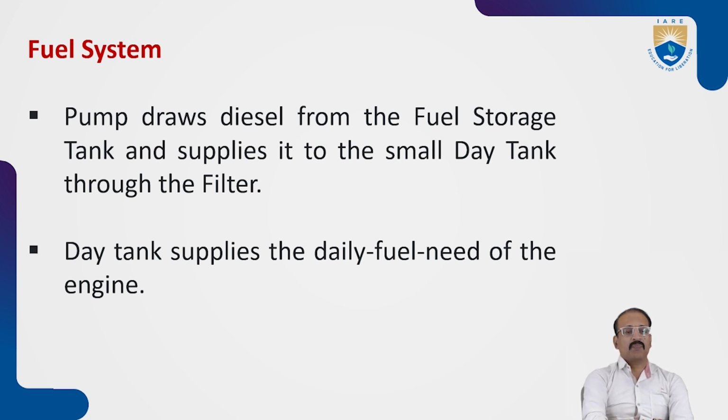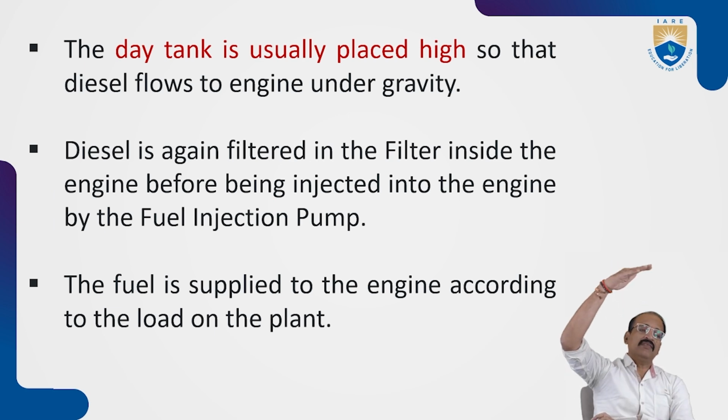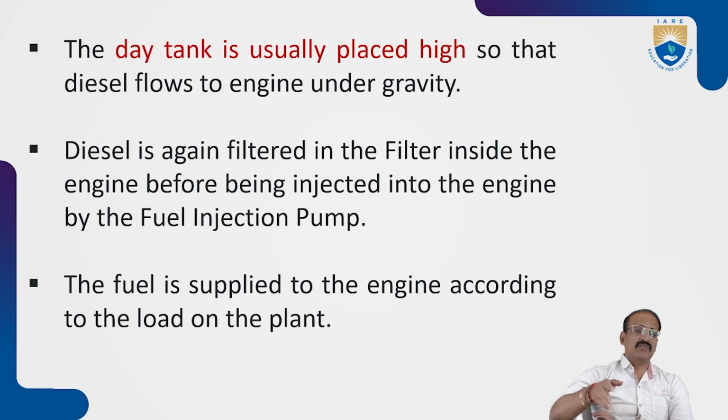Fuel system. The pump draws diesel from the fuel storage and it is stored in the day tank. Already we have seen it in the diagram. The day tank supplies the daily fuel need of the engine, so that's why the name day tank. The requirement for the day will be stored in the day tank. The day tank is usually placed high so that the diesel flows to the engine. Generally it will be provided at a high level, so due to gravitational force it will easily flow into the engine.